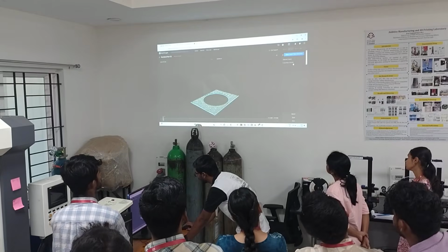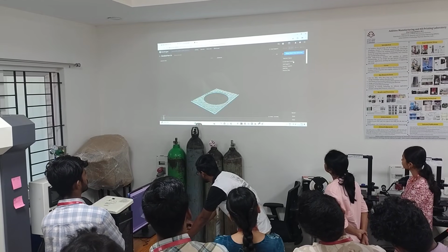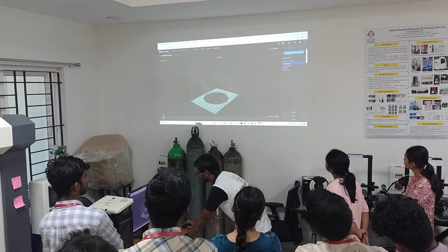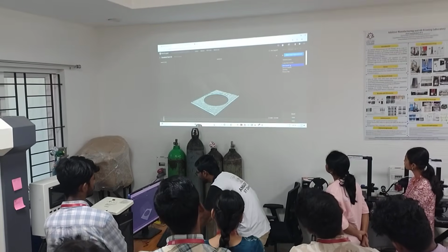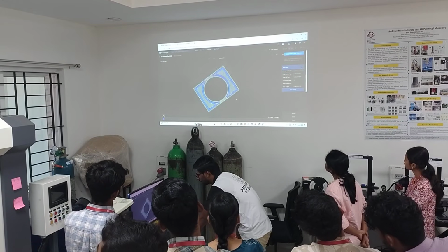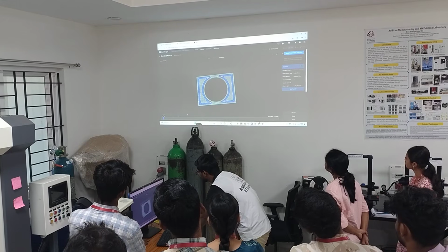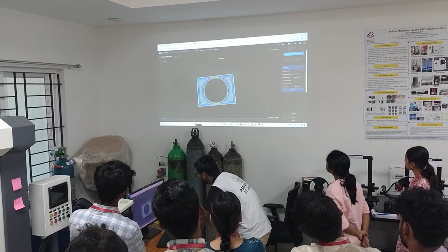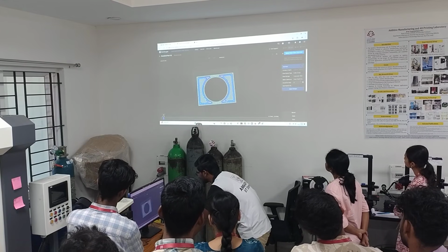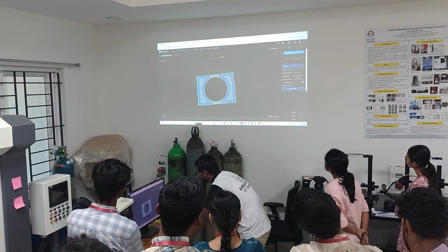How will I add it? I'll click on create new override. It asks me to add fiber, remove supports, or add supports. Since there is no support required here, I'll just click on add fiber. The fiber is already added here, and I can see it is on the 4th and 5th layer. It can be isotropic or you can make it concentric. I prefer concentric most of the time. And it shows it is only 2 layers.